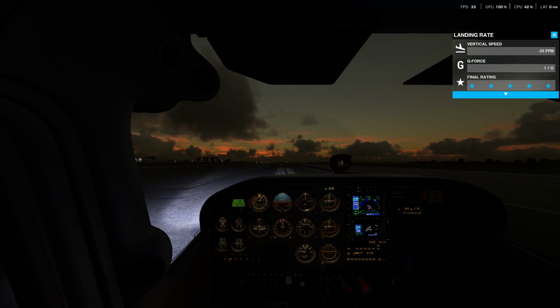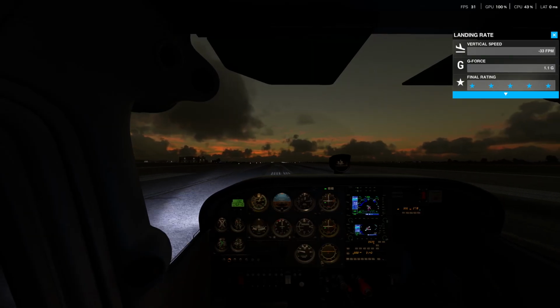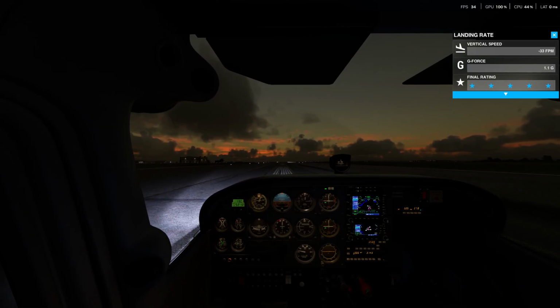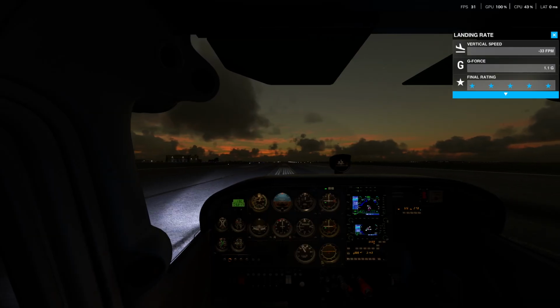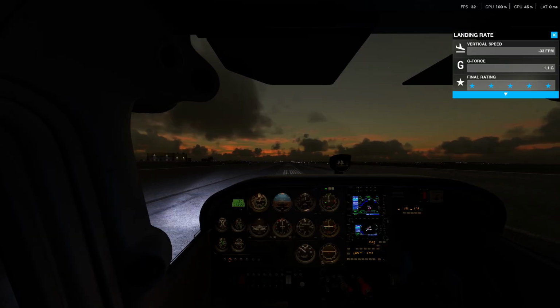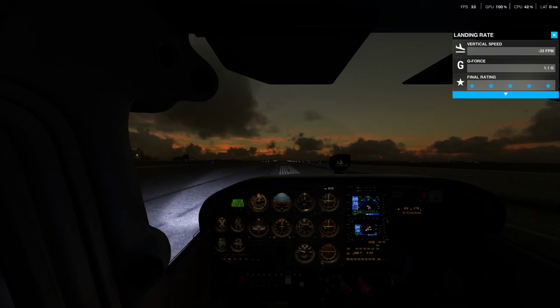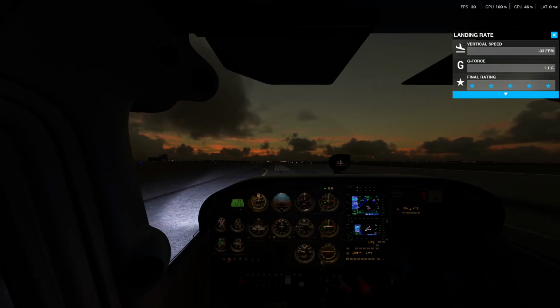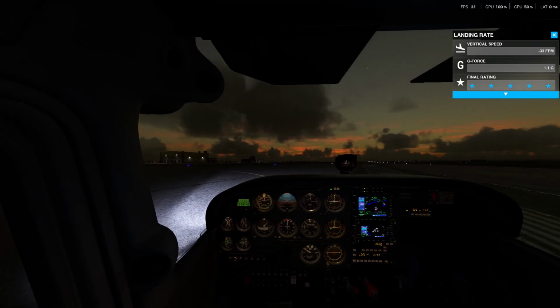Alright, so we're going to go flaps up here just to decrease our lift. I'm not going to use as much brake right now. We're still building speed from the taxiway. So we'll go ahead and increase our RPMs there just to get up to the taxiway. Which is just coming up here. I find that rudder control on the default 172 is kind of lacking. Kind of all over the place right now, that's fine. Alright, so we'll go ahead and maintain about 1,000 RPMs. We'll keep the speed going.